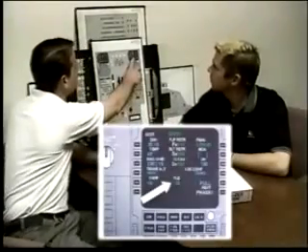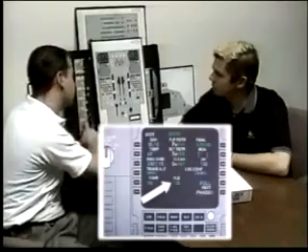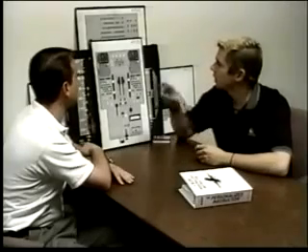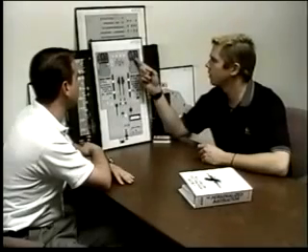Describe to me the difference between this VLS and the VLS you find on your PFD. Okay, the VLS down here is generated by the FACs. It's a dynamic number which changes quite regularly, and it's based not only on gross weight, but angle of bank, load, and all these other factors. The number up here, VLS, is generated from the FMGC and is based specifically on your gross weight. And all we really use this for is to develop what our V approach is going to be.